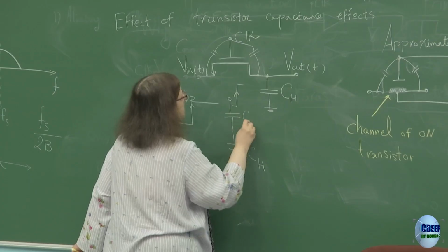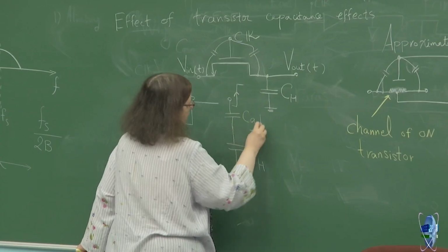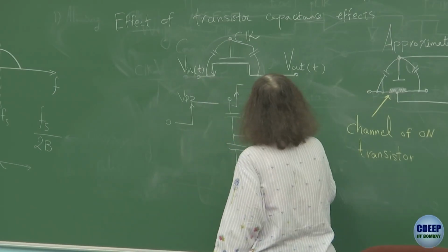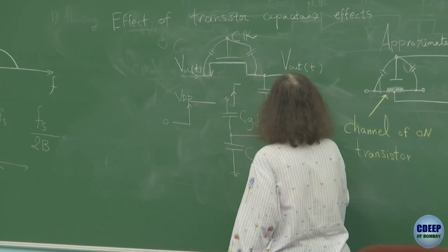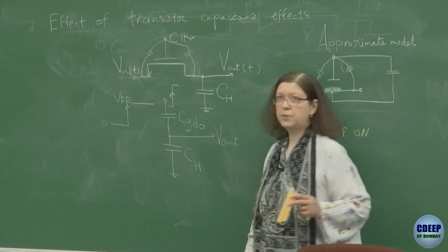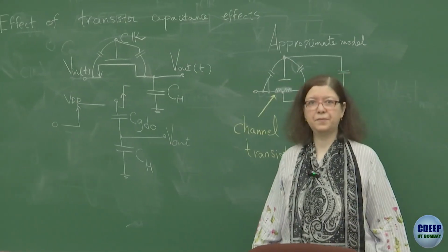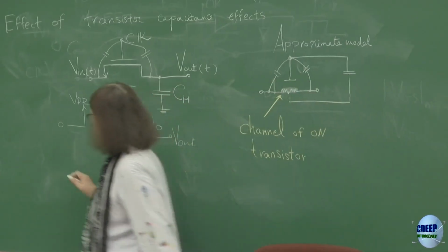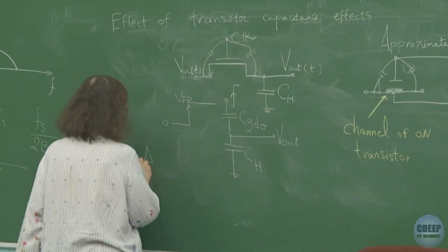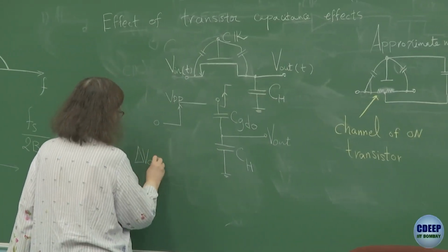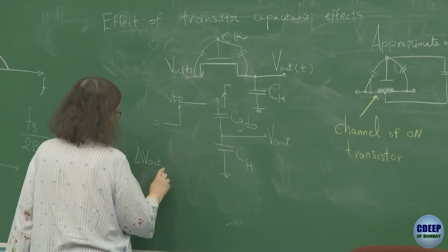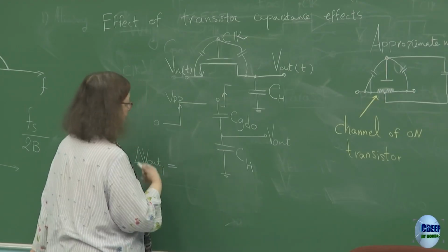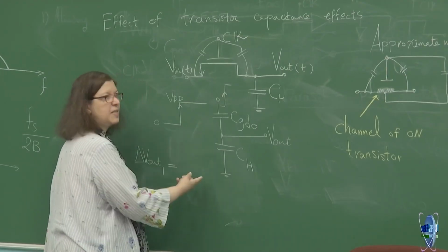For the case where the clock edge is very sharp, now you see there's a capacitive division. So therefore, you will experience the first delta Vout, delta Vout1. The first effect is a capacitive division.